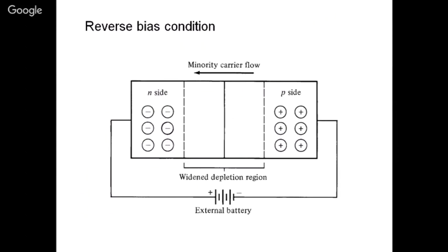Then the LED, as I said, is the base. Reverse bias the LED and it becomes a detector. So they could work very fast, because before that they had photo cells, photo tubes, and photovoltaic cells, with which you could detect light. Photo transistors then came up, and then for the requirement of communication, they had to develop special detectors. But once again, the starting point was the PN junction. And now a reverse biased PN junction acts as a detector.